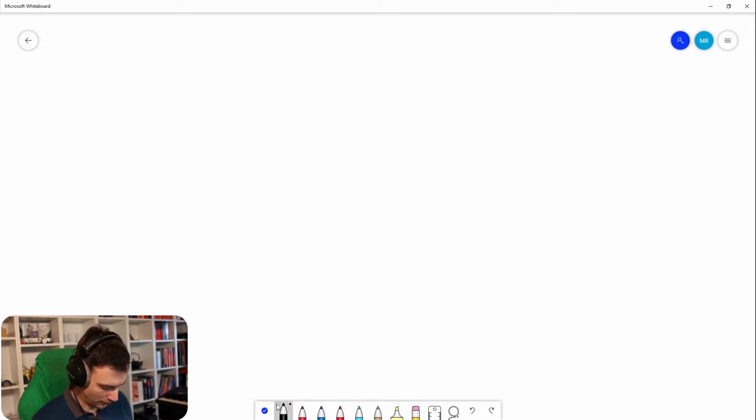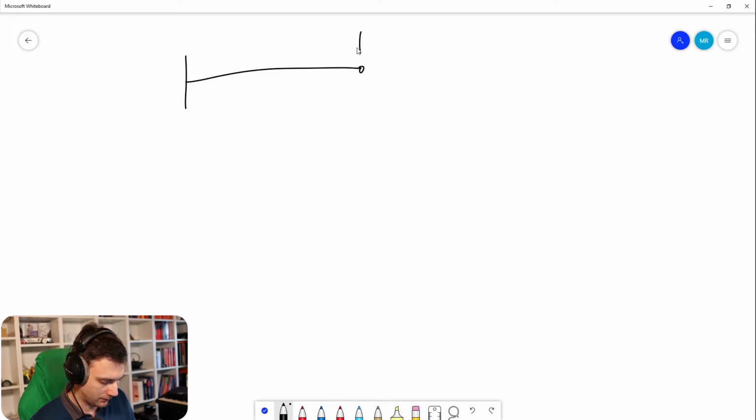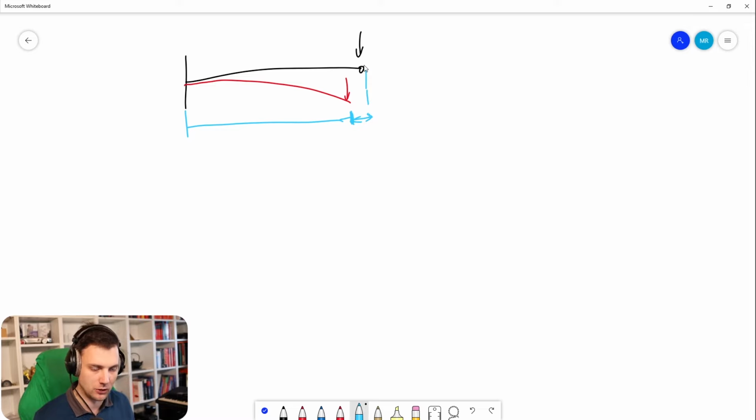So let me just quickly show what I mean. We have, for example, our cantilever beam, right? And we have a loading here. And this cantilever beam, because of the loading, it deflects. Now, first thing is the geometry changes. You see as it deflects until here, the lever gets shorter, right? So it was this long, but it gets shorter because of the geometric deformation. And this makes the structure change the stiffness matrix because you have a different system. You have a deformed system now.